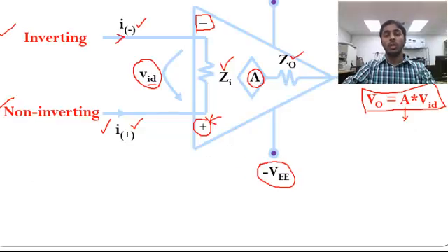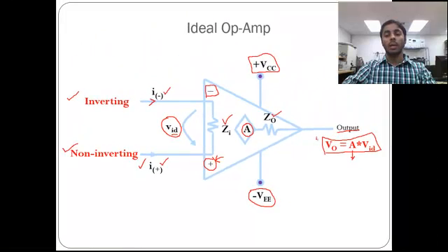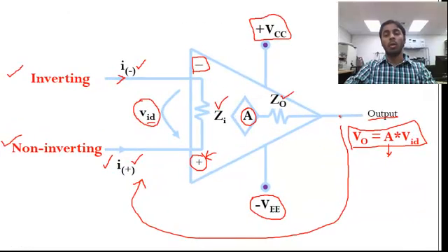So in the previous figure, there is no loop back. The output signal is not fed back into the input side, so that's why this configuration is treated as an open loop configuration. Whenever you see feedback, no matter whether the output signal is fed back into the non-inverting terminal or the inverting terminal, those are referred to as closed loop systems.